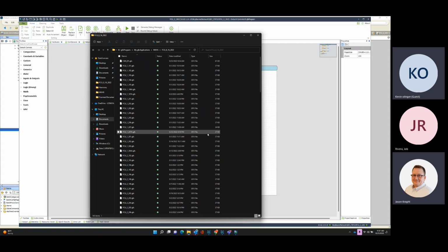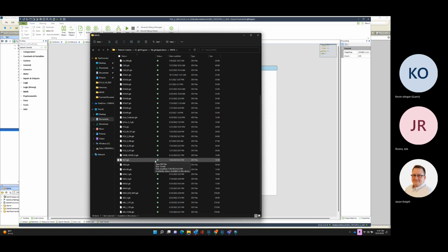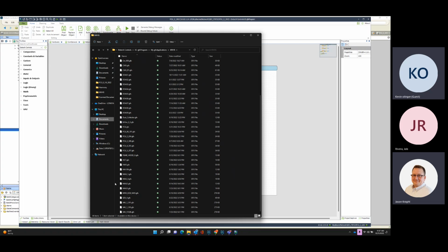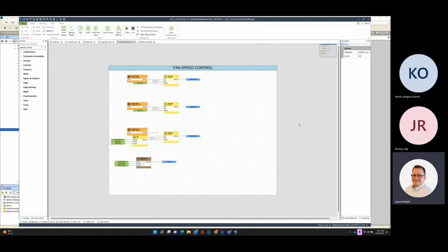because some of the min speeds were 3%. And so I went to the balancer and I said, where did you guys come up with that 3%? Is that a calculation? Did you actually override the fan to 3% and then read your registers, and that's what you needed for pure ventilation mode? And they're like, yes. And I'm like, okay, well, I'm running the fan at 3%. My fan status is in alarm and the fan motor is not even turning. So I've had that argument back with the engineers.